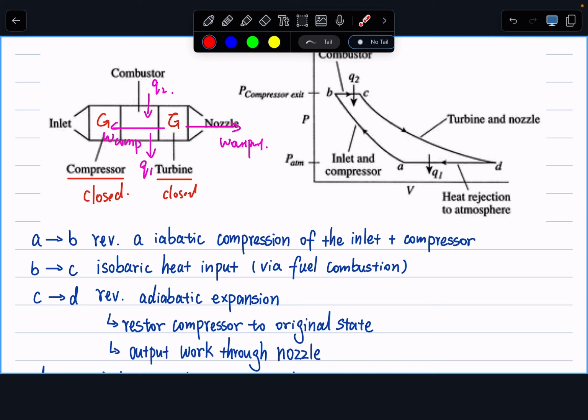It's not super hard. For example, we have adiabatic compression. So you know that from A to B, the volume must go down, right? From B to C, that's isobaric, and heat input, so the pressure is the same, it's a straight line. Heat input, so your temperature goes up, the volume must go up, right? So knowing how to plot these PV diagrams is important.